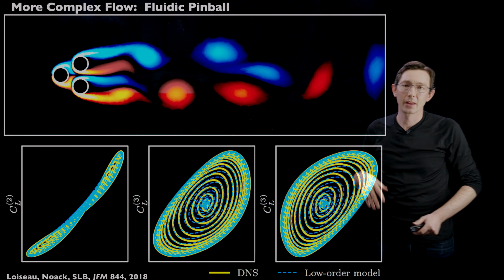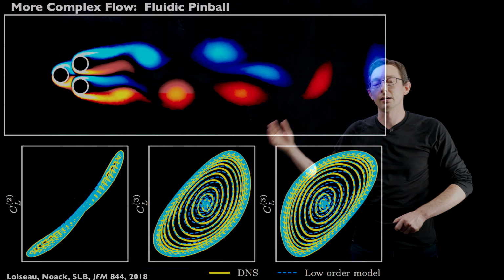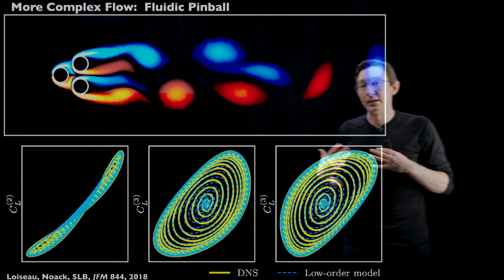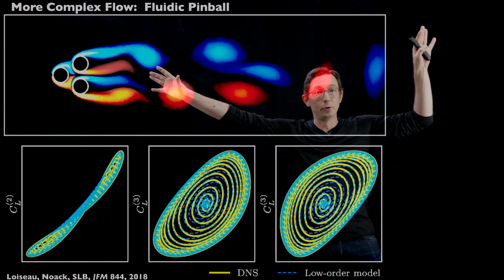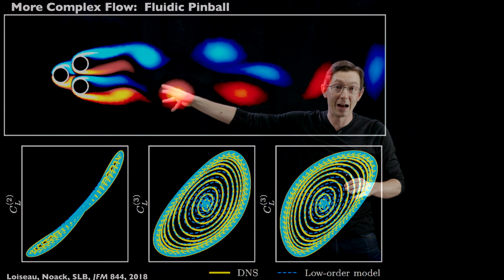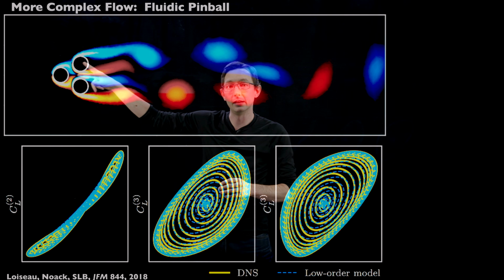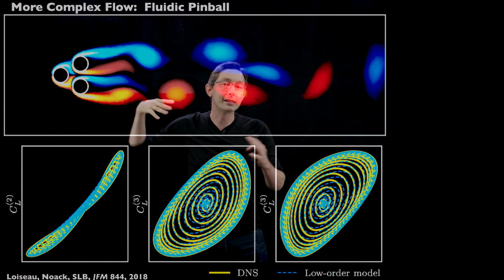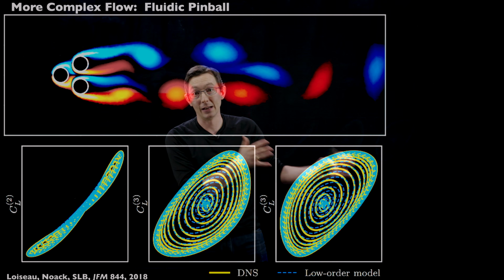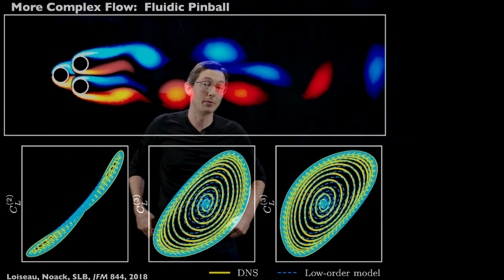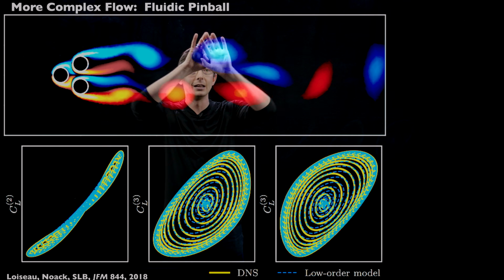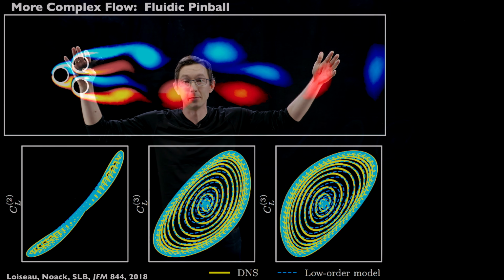So that's really cool. And since then, working with JC and with Brunton and Noack, we've been able to show that you can also develop these models without having access to the full flow field, without having full flow measurements. Even if you just had lift and drag measurements, in this case on these three cylinders, you can still build very, very accurate SINDy models kind of in these lift and drag coordinates. So this gives us some hope that we can actually use this for control in the real world, because we don't need access to the full measurements to have these models work.